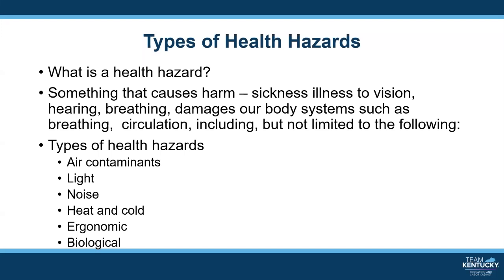These air contaminants are created from the high heat for melting the metals, the flux, and the shielding gas. This creates smoke, gases, and fumes. This process changes the structure of the solid metal into a metal fume, which is a metal in a vapor form while it is still hot.